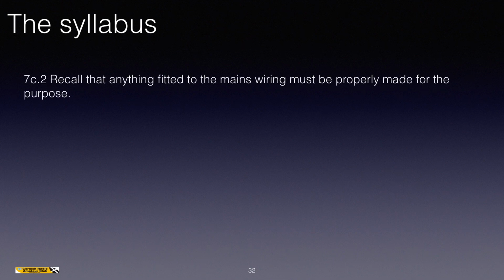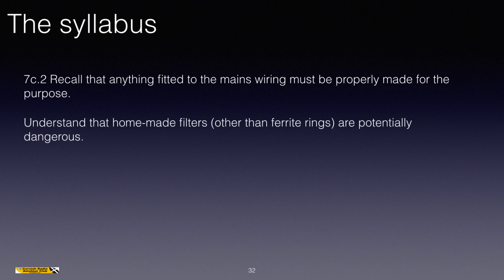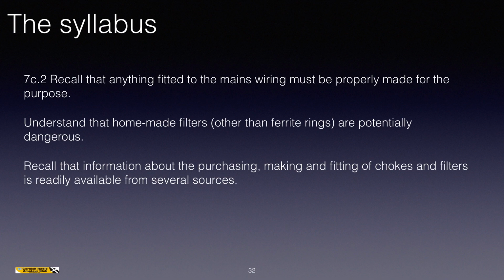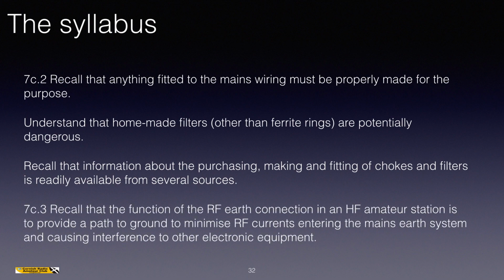Recall that anything fitted to the mains wiring must be properly made for the purpose. So here they're saying don't go dabbling around opening up covers and fitting filters internally yourself, or designing or building them yourself, because that is dangerous. And other than ferrite rings, homemade filters are potentially dangerous. Recall that information about the purchasing, making and fitting of chokes and filters is readily available from several sources.